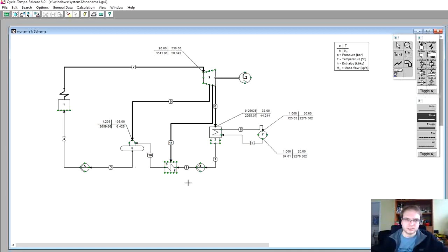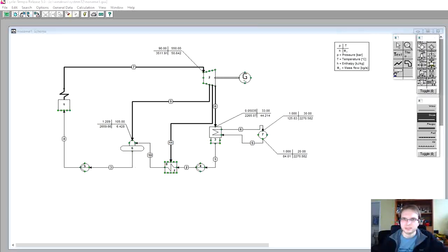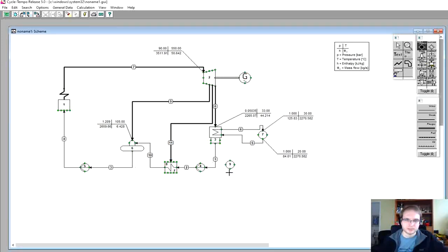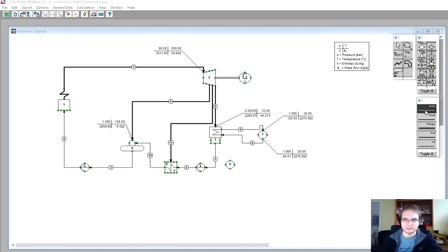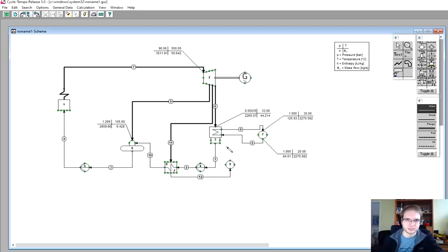But in order to have pressures and pressure drops in the way we want, let's add one more component there, a sink or source, which will act as a pressure separator, or, let's say, a throttling valve between the feed water heater and the condenser. Otherwise, the condenser pressure would propagate on this line towards the feed water heater, and the calculation would not run correctly.